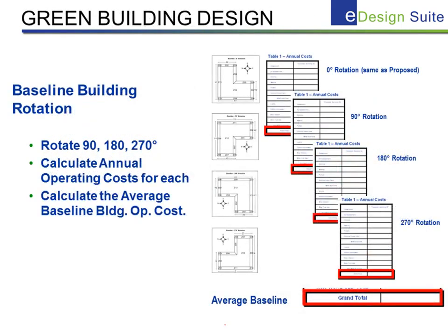The third major function of HAP has been for green building design compliance. The LEED rating system references the ASHRAE 90.1 performance rating method. HAP automates key portions of this procedure. An example would be the 90, 180, 270 degree rotation and operating cost averaging of the LEED baseline building. The software will accomplish this detailed task in a split second.